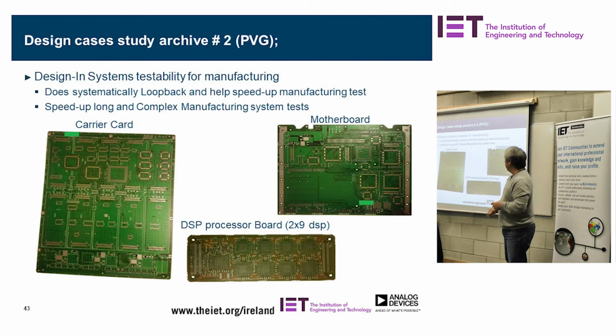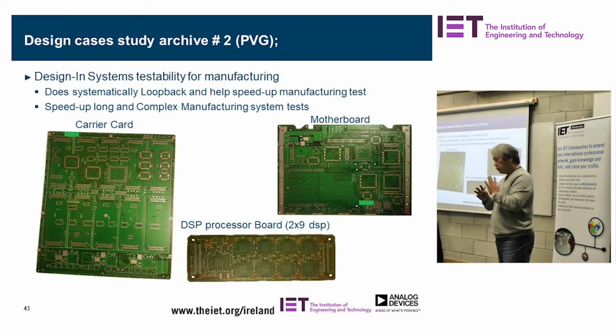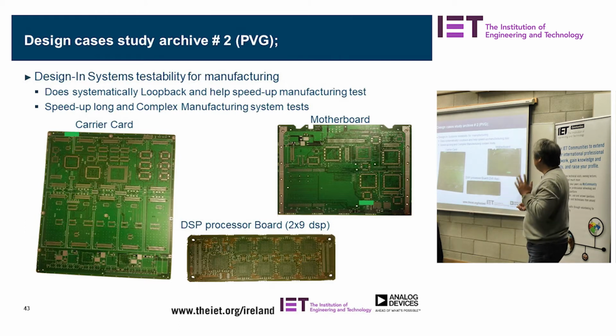They're so small. And it was a challenge even laying this out because you have BGA on both sides. And this is a module with ASICs and FPGAs on it, memory, RAMs, buffers, and we tried to JTAG over 200 devices, a challenge in itself. So we tried to JTAG 200 ICs. That was a challenge in its own right.